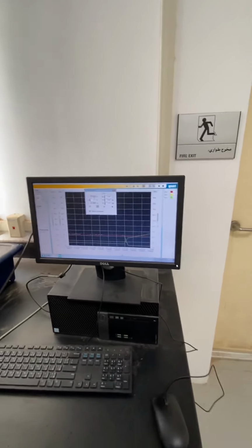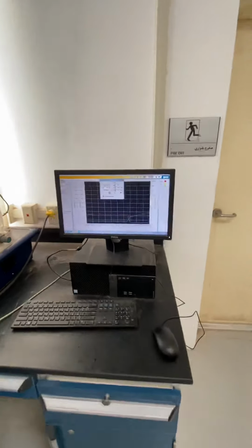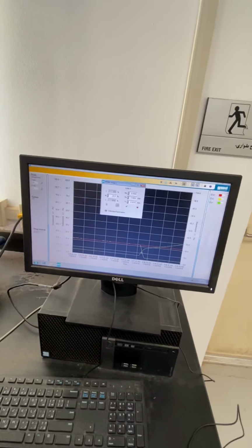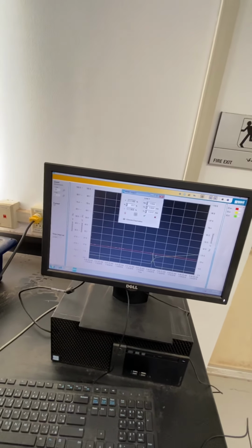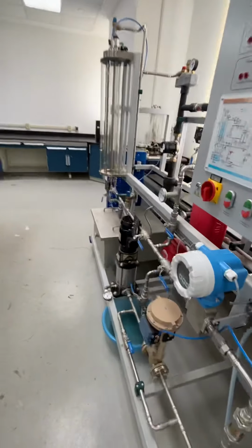The feedback control system doesn't know what problem has occurred in the system, guys. All it knows is that it received a measured value from the sensor, and this value will be compared to the set point, and based on the error it will take an action. Right now the controller is telling the pump to increase its speed.